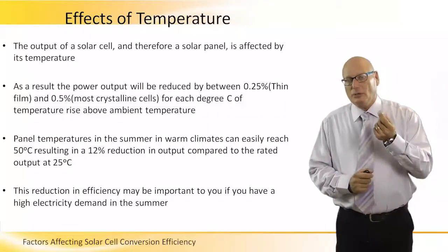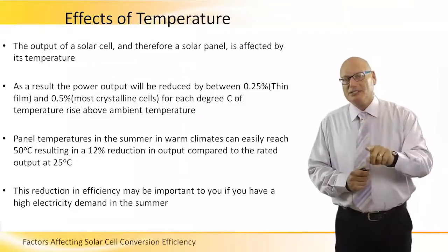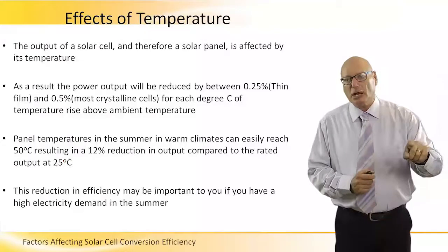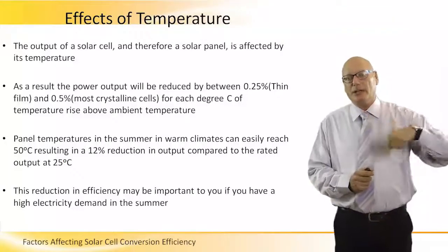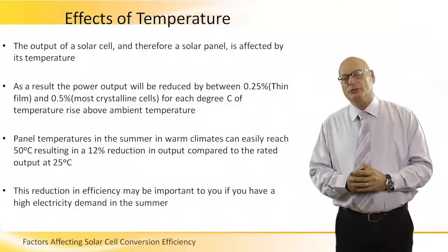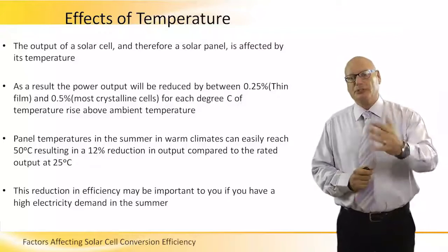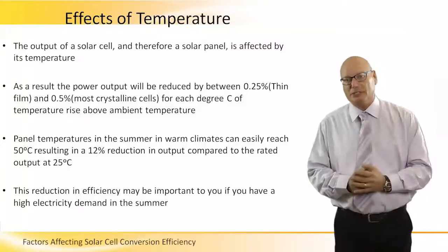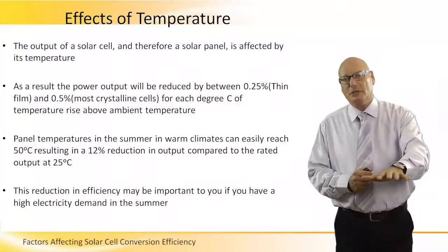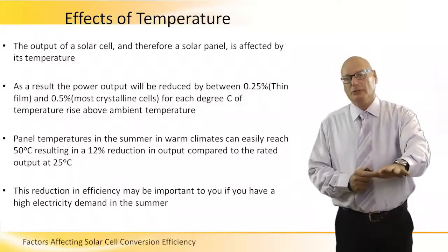So we better look at the technology of the panels and make the right selection according to the environmental parameters of the location of the PV system where we want to install. In the desert, for example, where surface temperature can go up to 70 degrees, we touch the surface, we touch the glass of the panel, and it gets very hot.